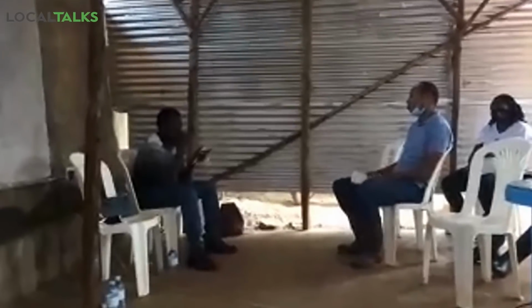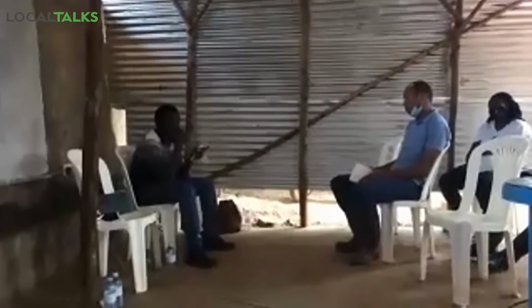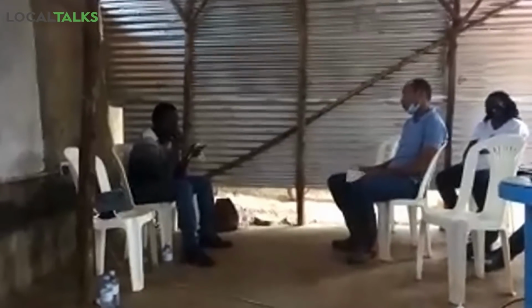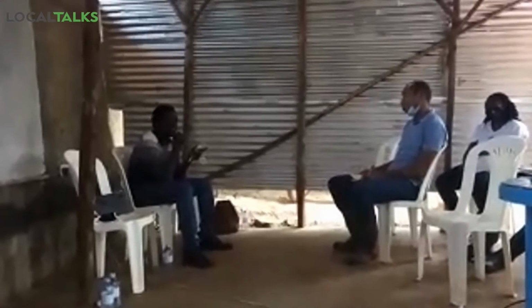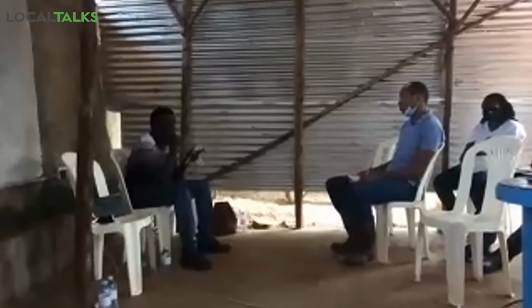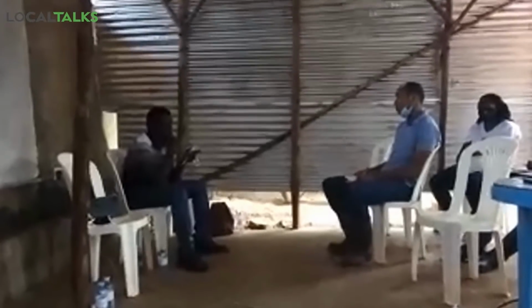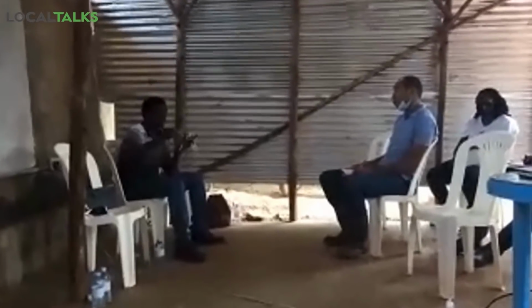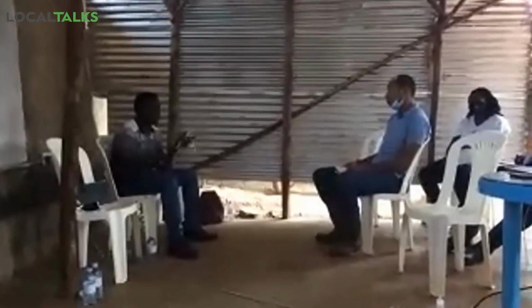I don't remember the exact figure, but it was extremely low. I think it was really coming to like 0.1 megapascal or something. Very, very low, that could be resisted with anything. Of course, because of the shape, when you put in the shape of the walls and the size and the mass of the walls, it actually reduces the need for tensile reinforcement.